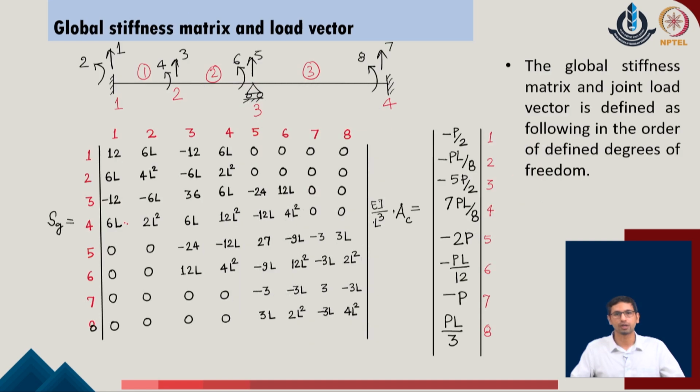With this point, now we can move ahead with the contribution of the individual cases with respect to the free and the restrained degrees of freedom. In the original problem, the degrees of freedom which have been identified are all in the global or the standard order. Now, out of that we need to identify the degrees of freedom which are free and restrained in the given system.